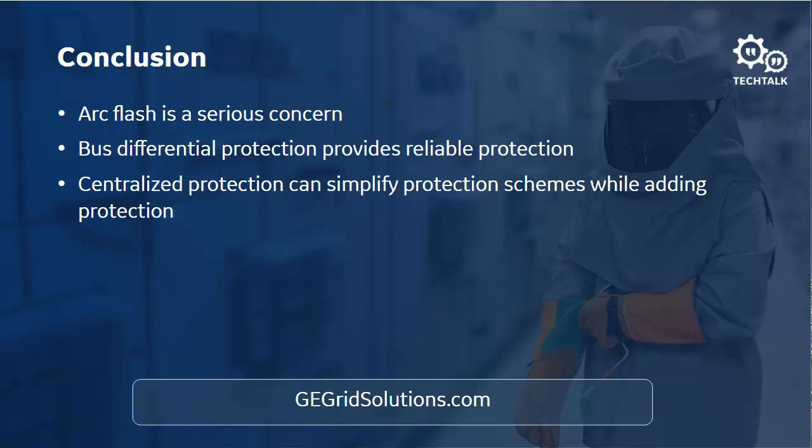What does GE have for a merging unit, say, to upgrade an existing breaker cubicle, and does the merging unit control the breaker and read CTs, PTs? So we have the MU320E. This one can bring in currents and voltage information and alarms and contact outputs. So we can do trip, close, we can provide lockout functions, bring back alarms, and the currents and voltage signals. So that would be the MU320E.